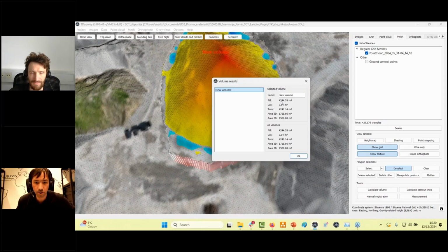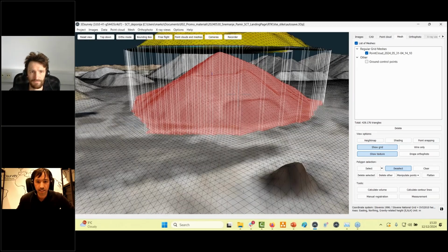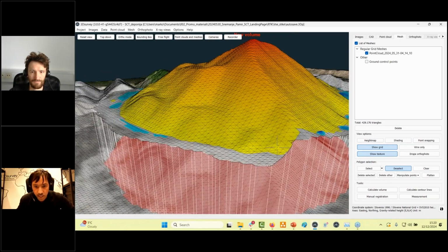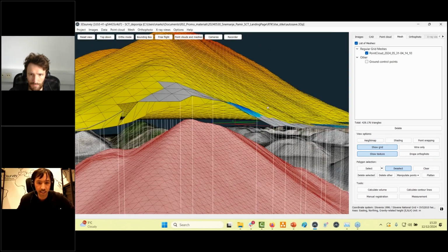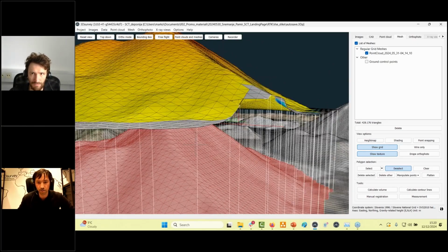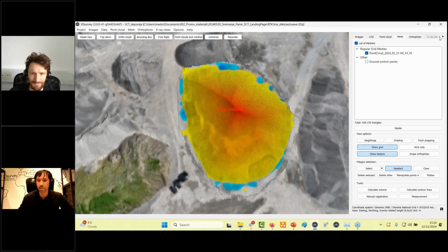We see here 4,244 cubic meters of fill, a bit of cut, total area, 3D area, 2D area, everything like that. I just confirm it. I see it like so. And this is the fastest way, maybe not the best one, because the lower surface, you can see it here, but it's not so nicely visible. So I maybe didn't select enough here, and that's why it's not connected straightforwardly here, but I did this on purpose.